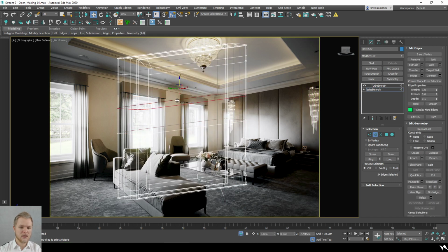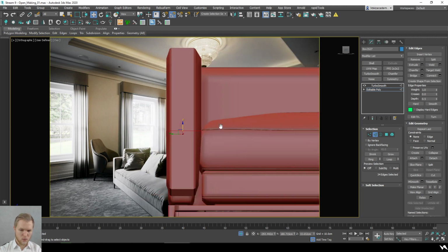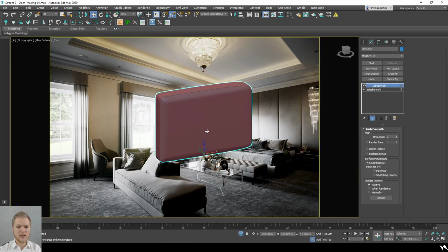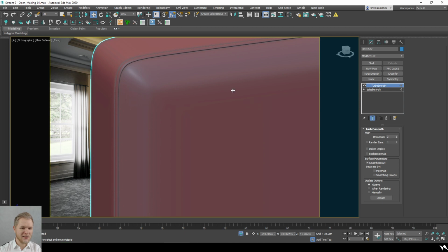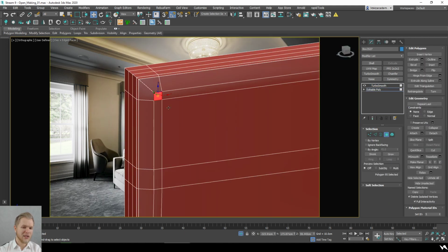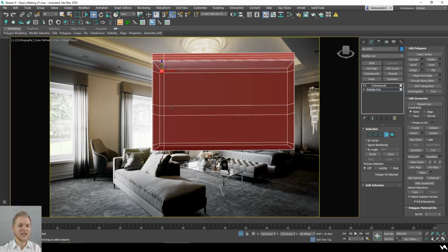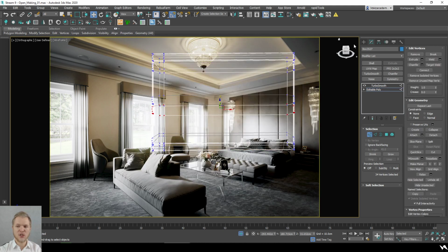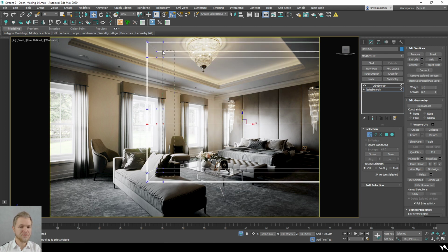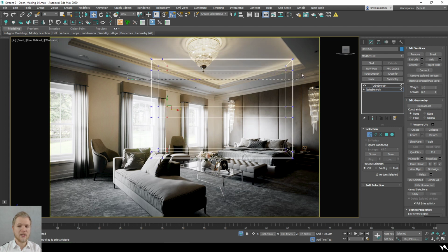even better effects. So let's move this downwards, again downwards, and we're going to get a bit better effect this way. So as you can see, it's getting nice and smooth, but we're getting a little bit of pinching around here. So to avoid it, we can relax this by increasing the distance between those edges. We don't want to necessarily create this edge too far away, but you can move it just as I did right now, and the pinching is not going to be visible right now.